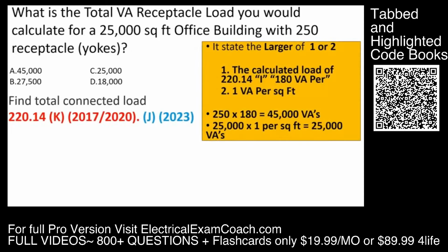To do that, we're going to head to 220.14(K) if we're in the 2017 or 2020, and we're going to head to 220.14(J) if we're in the 2023. Same information, different name. Both of them state that we must select the larger of 1 or 2. So we're going to do 2 different calculations and select the larger of the 2.